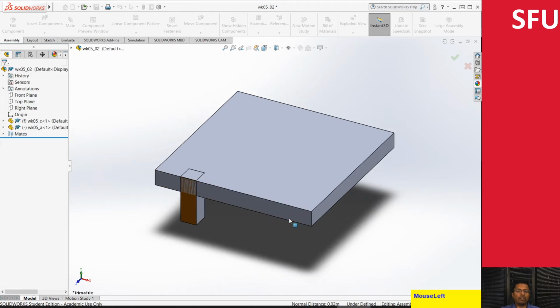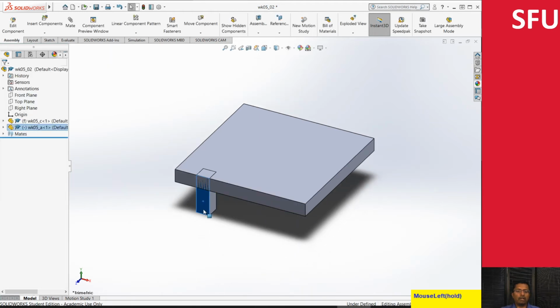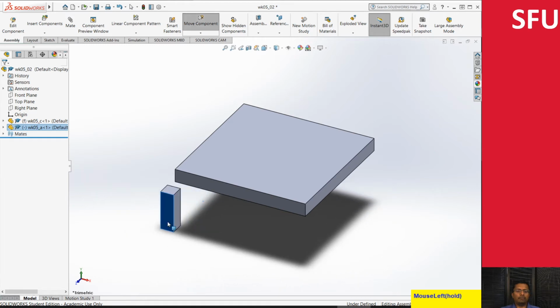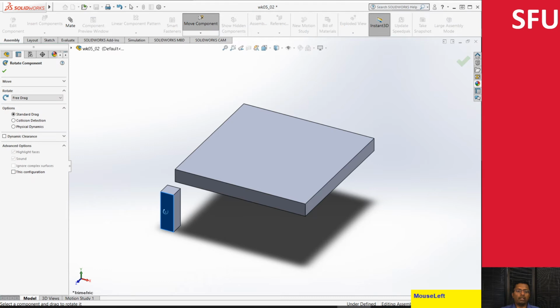I'm going to say okay just to show what we have here. So I can basically make this and then still move this part. I can actually list my constraints over here. I can click and it says I've made these two faces coincidental. I can check that by rotating my part. I click on the part here, and within move component I have rotate. Here it has free drag, where I can rotate the part like so, and then say okay.